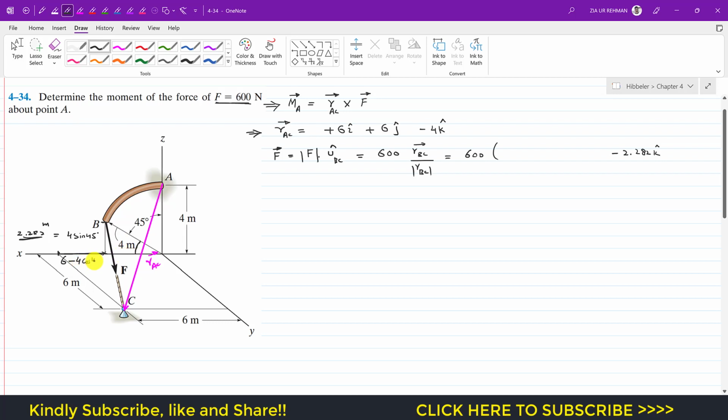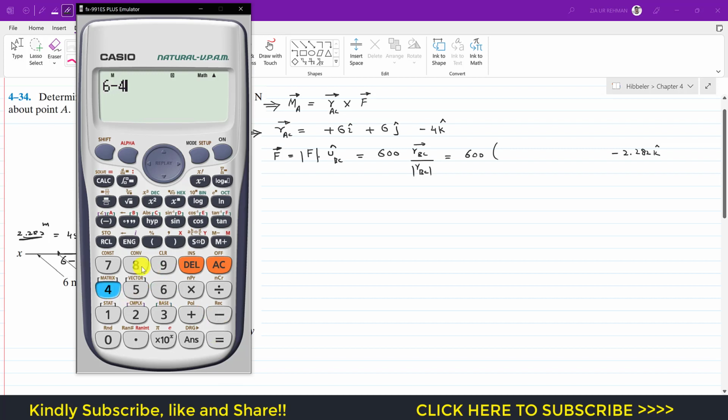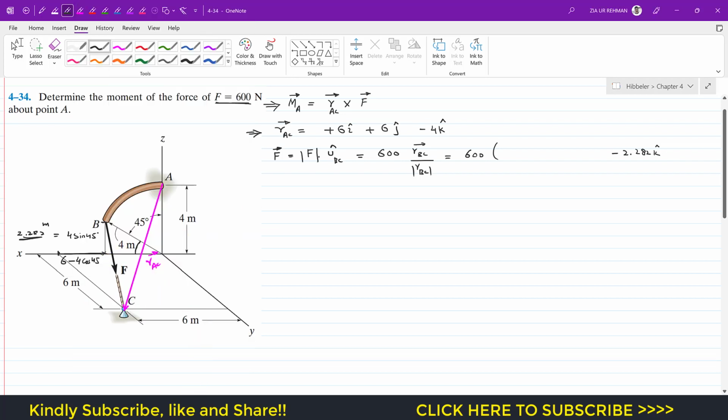So this is 4 cos of 45. So 6 minus 4 cos of 45 is the distance we need to travel in the positive axis, that is 3.171, or we can say 3.172 approximately. So this distance we have to travel, this 3.172 meters distance, in the positive i direction.